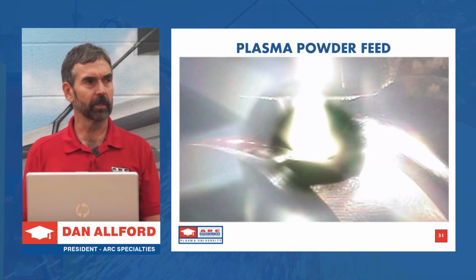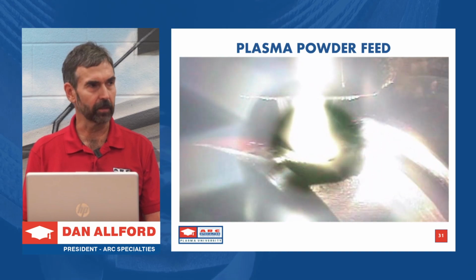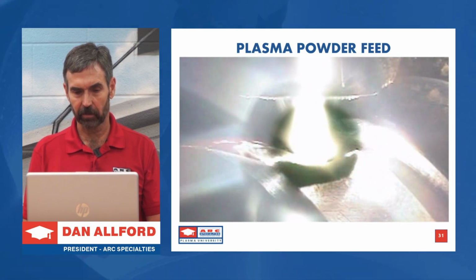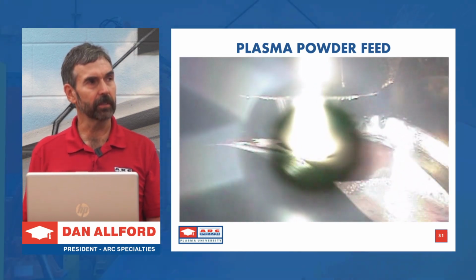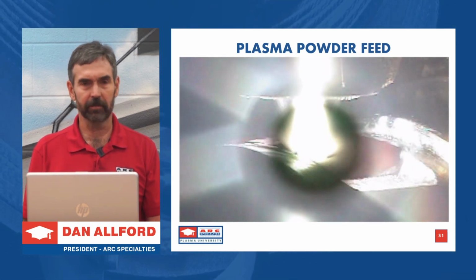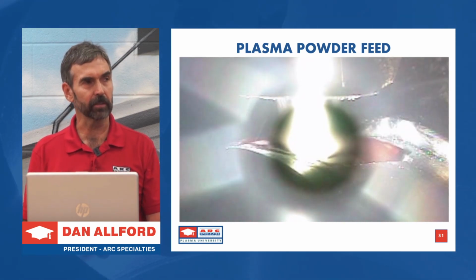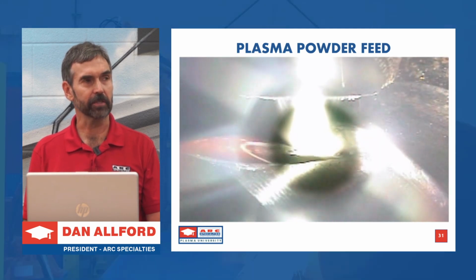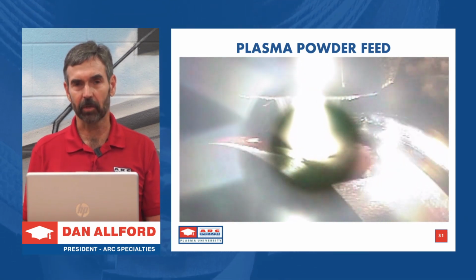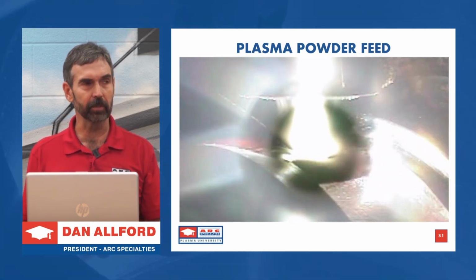So this is a video of an overlay weld. What you're seeing here is the part's not moving, but the camera is actually mounted on the torch, and you can see that the torch is oscillating back and forth between the walls of this narrow groove. And if you look closely, you'll see columns of powder coming in from the left and right. What we're putting down is a high cobalt alloy. This is about 58 Rockwell C. What's interesting about plasma is you can actually produce crack-free welds on these high cobalt, high hardness alloys without preheat. My suspicion is that you're not chilling the puddle with a cold wire or rod and you avoid that shock. So you're actually able to create crack-free welds, which you wouldn't have been able to do with TIG.